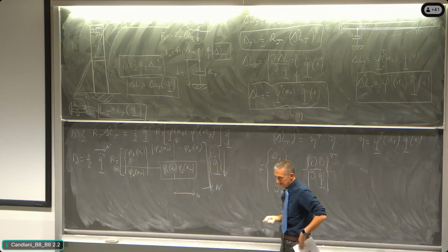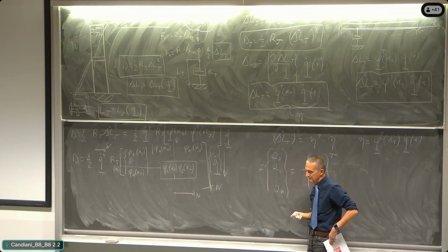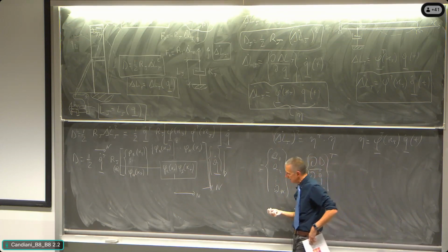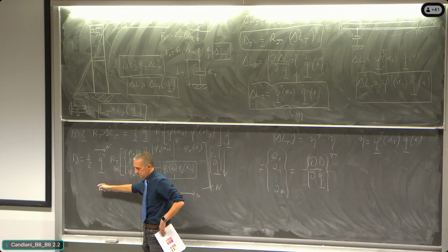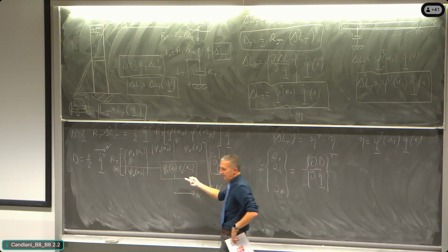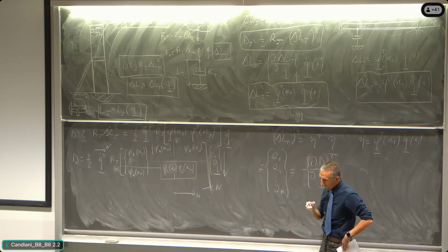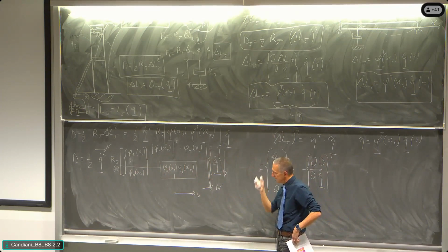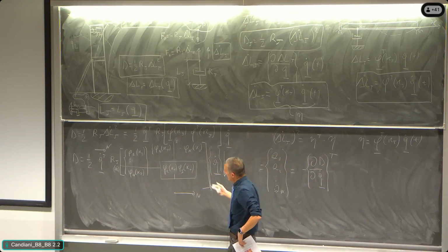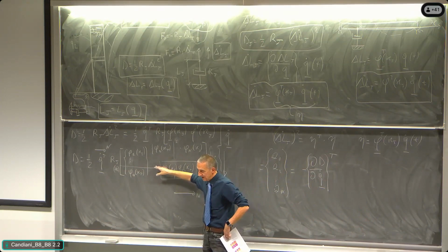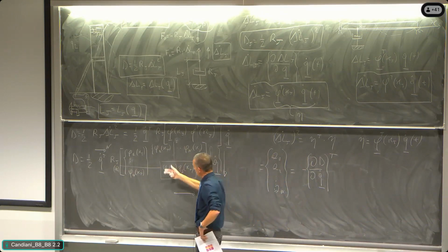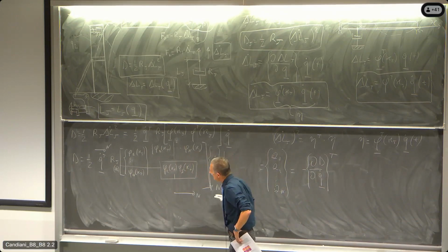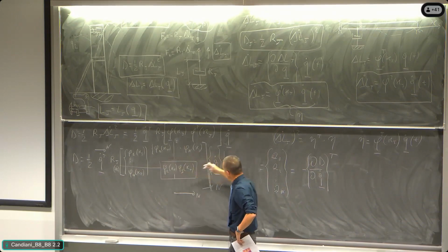Then, in the same way that it was done, and somehow a bit demonstrated, for the mass matrix and the stiffness matrix that are coming from the kinetic energy and the potential energy, this derivative with respect to the vector q dot, in case the energetic function is a quadratic form like that, and we made somehow an intuitive demonstration, the derivative with respect to that, considering the hypothesis that this matrix here is symmetrical, and it is symmetrical because the way in which we built it makes it symmetrical, is simply the matrix itself multiplied by the vector q dot.